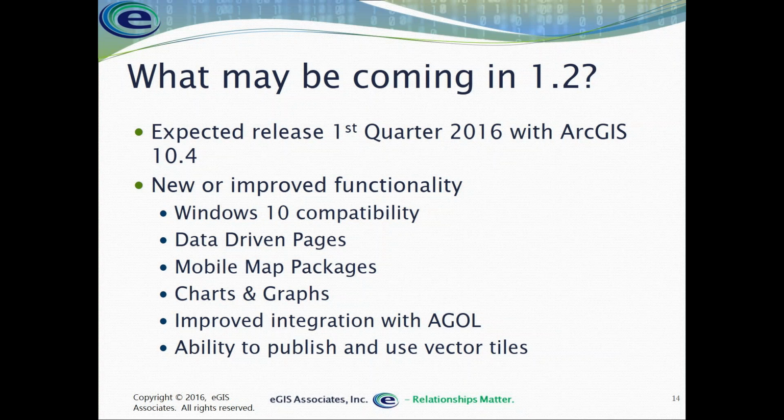Question was, what is the difference between feet and US feet in units of measure? The US survey foot is slightly larger than the international foot. It's like the fourth or fifth decimal place. I don't remember the exact conversion factor between those. I used to when I was land surveying a lot, but I don't remember it right now. But a US foot is not the same size as the international foot.